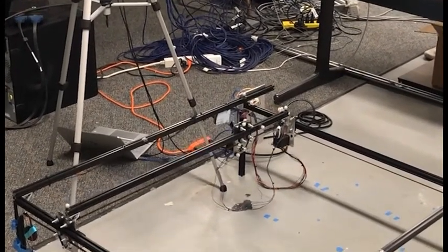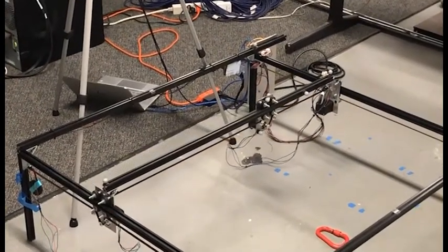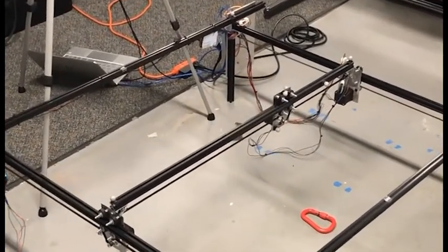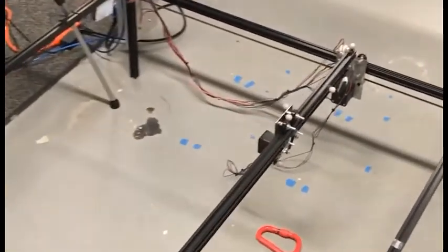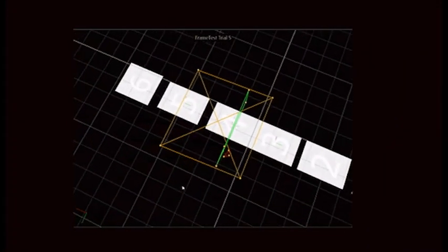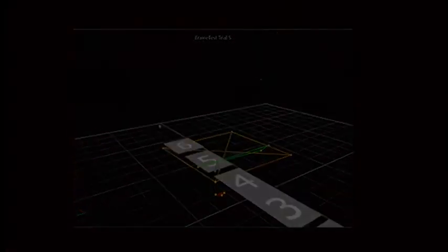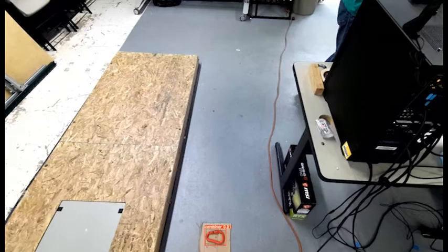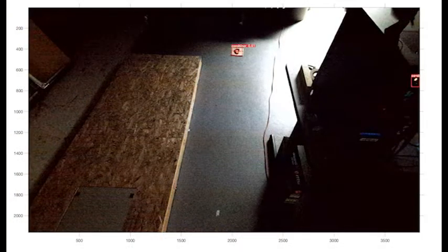Testing was conducted with three variables: lighting, target position in the XY plane, and target orientation. The data sets to analyze were target location relative to the depth camera, the trolley's final position relative to its preceding motor commands, and the trolley's final position relative to the target location in XY space. Testing the object detection separately, a test was done in order to determine the effect of lighting, distance, and orientation. The test was a degree of error experiment. A total of 24 images were tested. The YOLO5's centroid was compared to the target's true center, and the amount of false positives and false negatives were recorded.